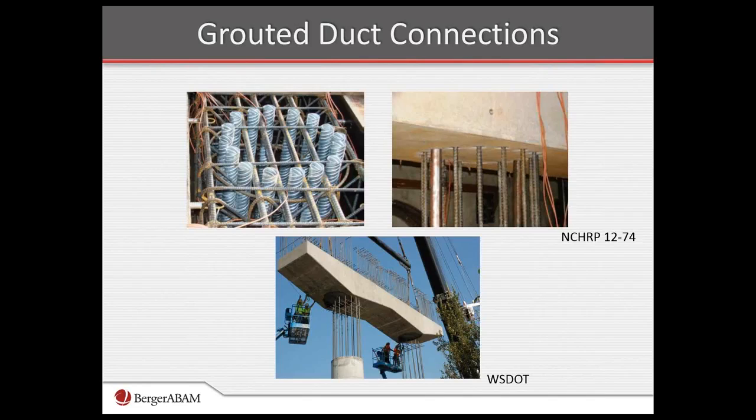And you can see that in certain parts of the curve of the circle of the ducts, you can pass no bars at all. Now, in the higher seismic zones or categories, there's quite a bit of prescriptive confinement steel that's required in these joint regions to keep the joint region from unnecessarily cracking and becoming a flexible and unintended weak link. In the lowest category, that confinement is not required, so that you have a little relief in terms of congestion and reinforcing steel for such connections.